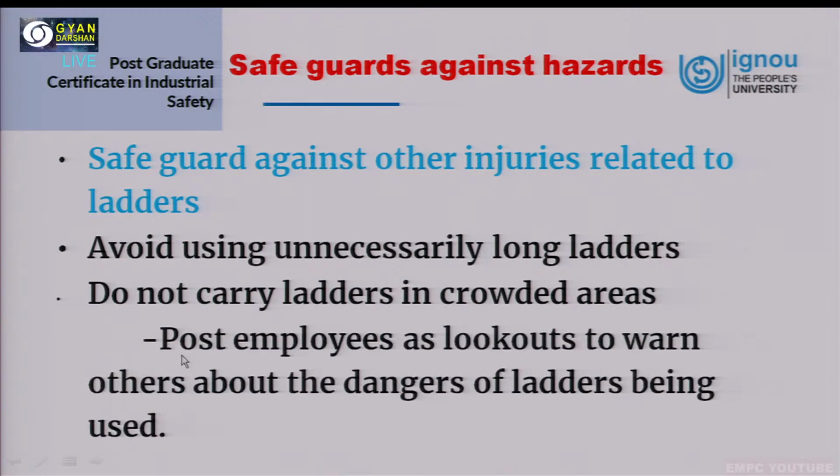The other thing that we can do is that we can also post employees as lookouts, to warn people that there is a risk of dangers of ladders being used. So it would be someone permanently positioned at the site till the time the task is over, to make sure that the people in the area are sufficiently warned about the risk of long ladders or huge ladders being transported around.